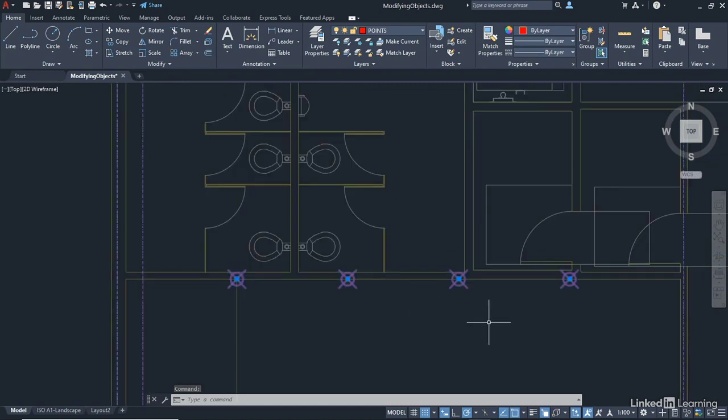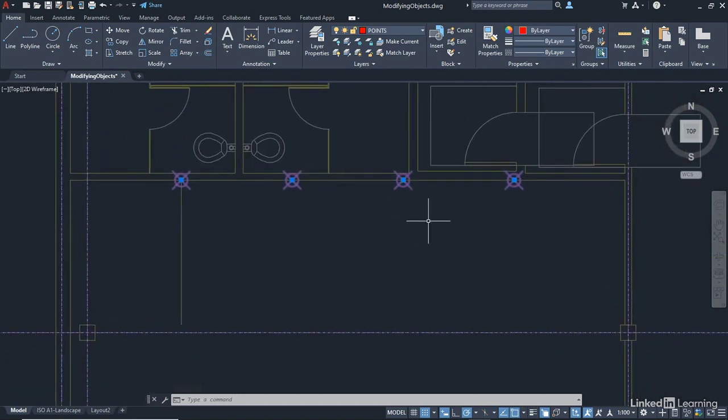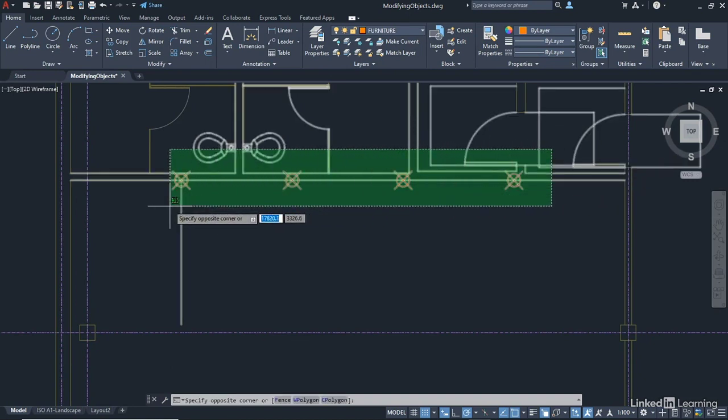And when I zoom out slightly, using the wheel on the mouse, you can see that I've only got those 4 points selected. I'll just hit escape a couple of times now to deselect them and cancel any command. Now, what happens if I do a selection the other way? That's known as a crossing window selection. So if I get in a space up here where I'm not highlighting any objects, click once and drag the other way, can you see how many objects are getting selected?